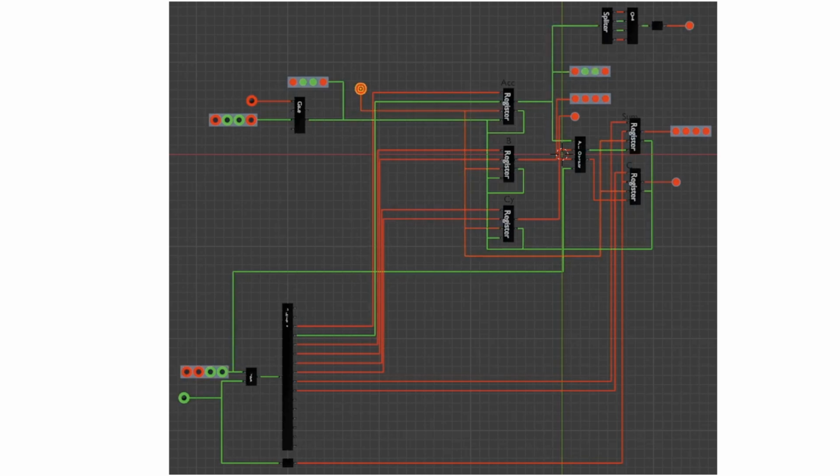This is where the actual ADD instruction begins. At the end there is the value 8 on the data bus. It will now be written to the B register. The addition is now requested via the command bus.